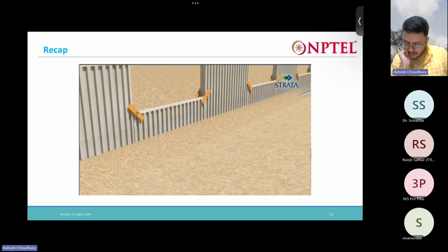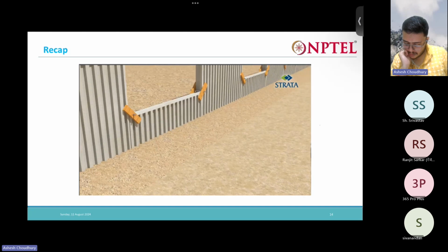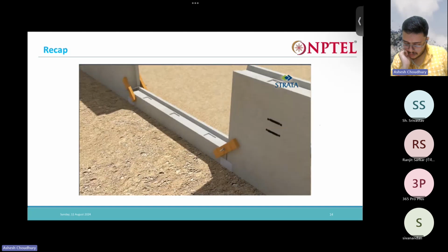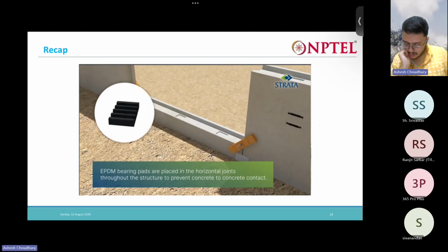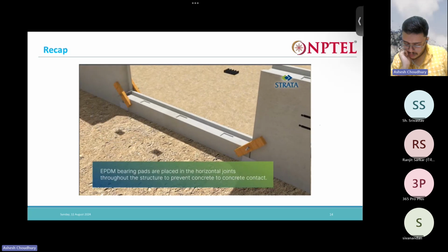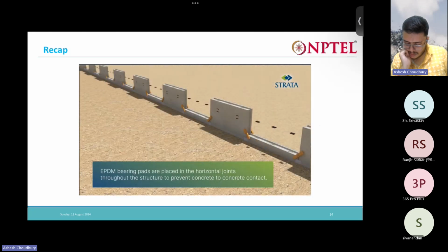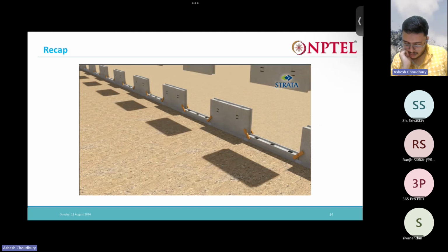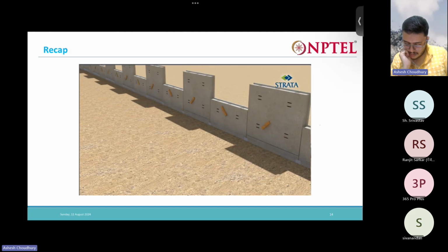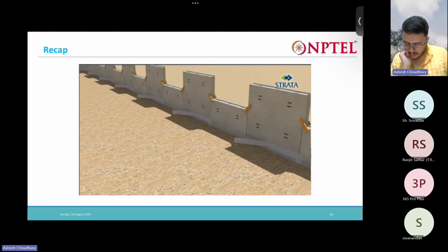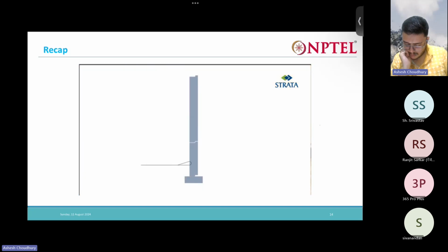Plinth protection to be added outside the wall to protect against crabs, rodents, etc. Approved geocomposite should be placed next to the panel fascia above ground level as per the drawing.